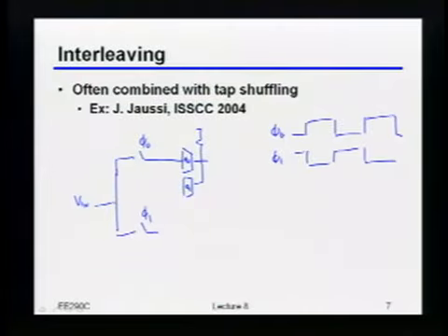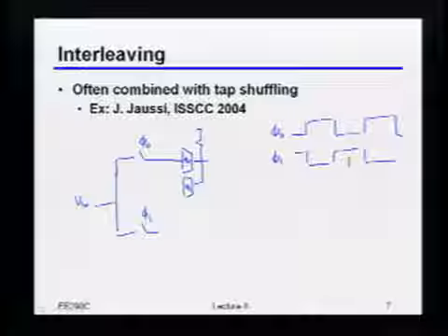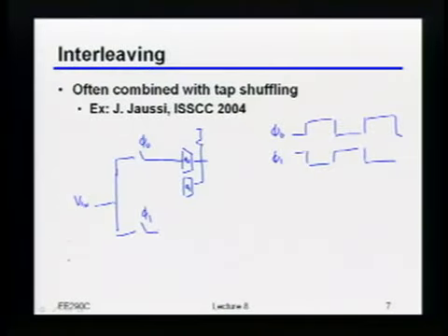Phi 1 maybe looks like that. Okay? So let's say that I was at this point right here, right? Then that would mean that my first post cursor, or rather I should say, the bit that came before me, was on phi 1, right? So in other words, if I wanted to build that filter, then I should just take this thing and feed it over here. Does that make sense to people? Or in other words, the sample that was on phi 1 is what happened one bit before me. So that's how I'm going to build something that has a z minus 1 in it, right?